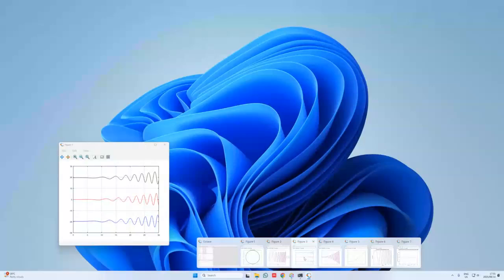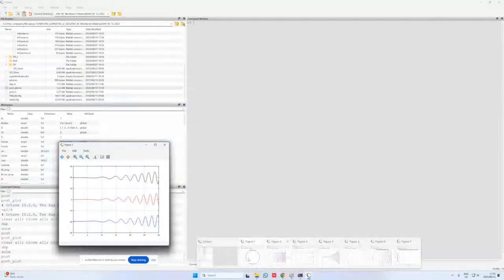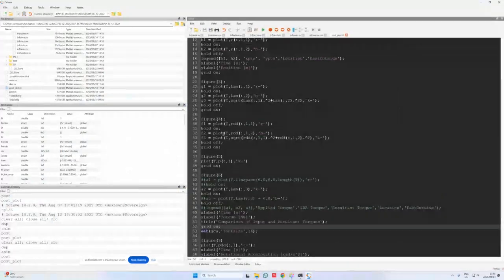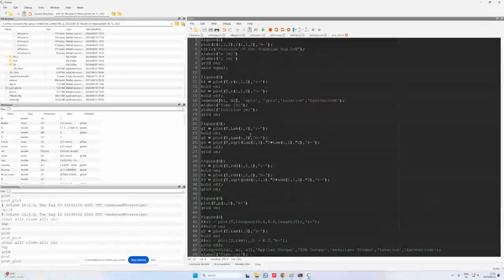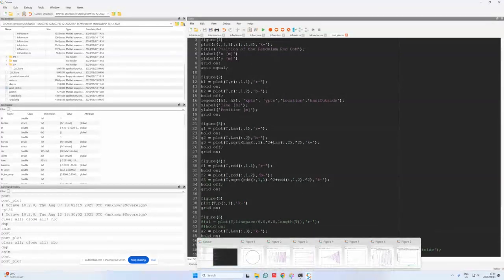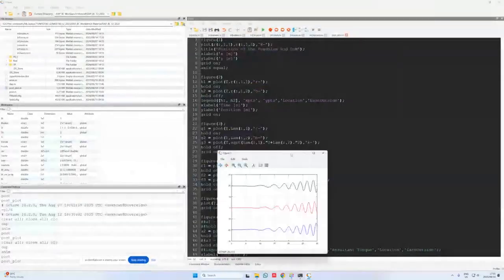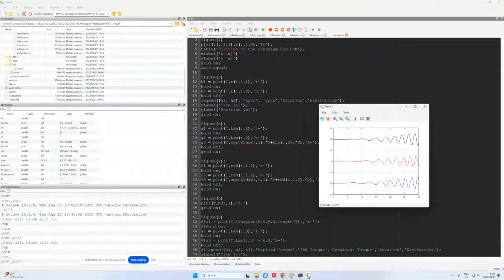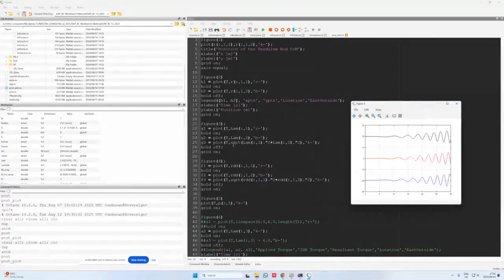Then figure 3 should be the, I believe this is, let me just double check. Figure 3 is then the reaction forces, so Lagrange multiplier 1 and 2. So the red line is the X reaction forces of the revolute joint. The blue line is the Y reaction forces, and then I can simply calculate the resultant force using Pythagoras. And this is then given as this black line that I have over here. In this case, I see oscillatory effects in the reaction force on the revolute joint, and I also see that the amplitude is growing over here.